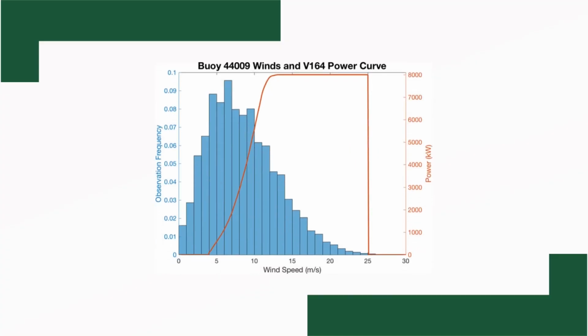The collected wind speed data is analyzed to create a frequency distribution. The data is categorized into bins or intervals of a wind speed range. The frequency distribution is visualized in terms of a histogram with wind speed on the x axis and frequency of occurrence on the y axis.